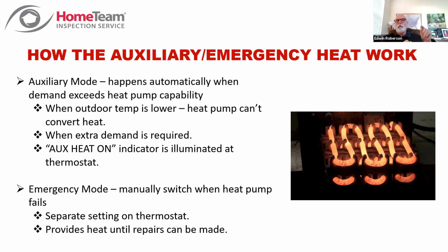If you have a heat pump and you go to your thermostat and you step through the modes, you'll find off, cool, heat, emergency heat. Well, emergency heat is a separate mode, and you would manually set it to that in the event that your heat pump just fails. Your heat pump's not doing anything, but you don't want the house to freeze. And you're going to get an HVAC contractor there just as soon as you can.